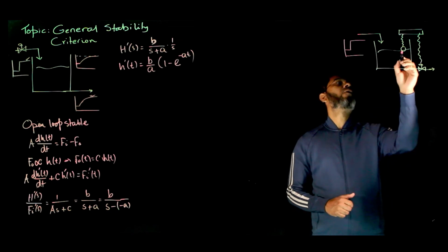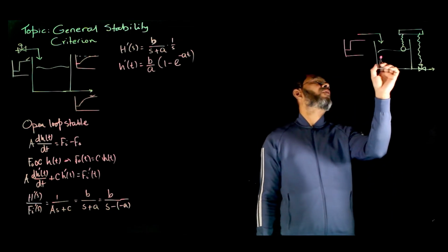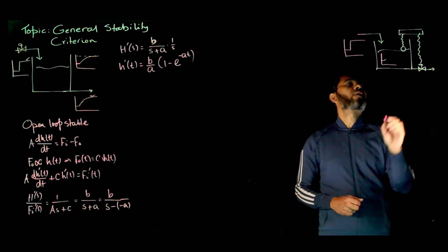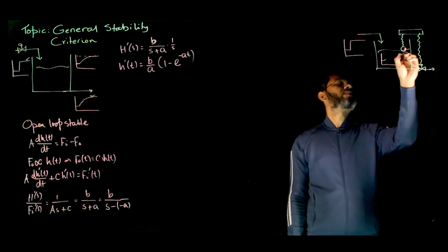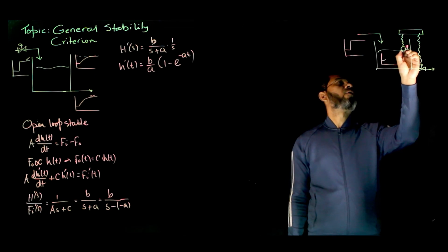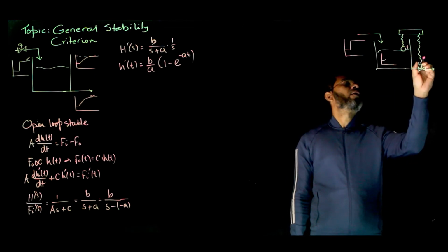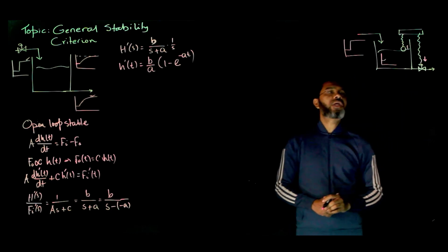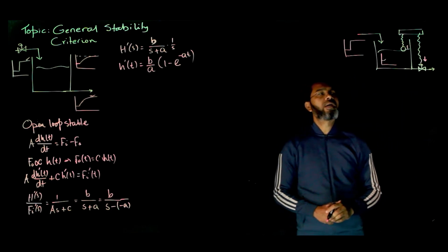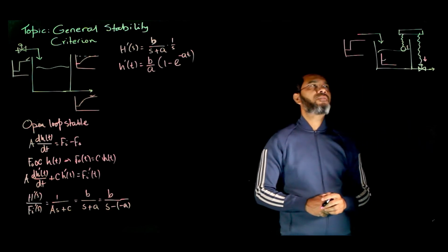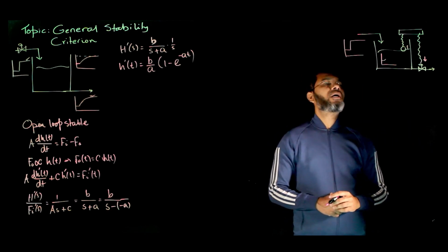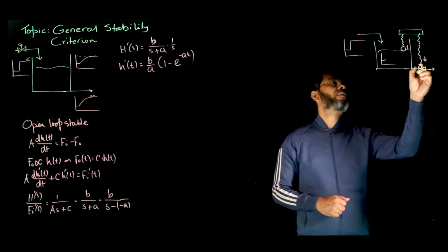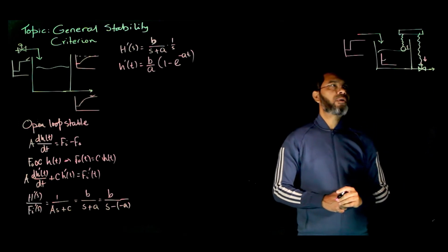We say that the level will go up. So for this case, the level will start going up. So when the level goes up, with this spring configuration, the float goes up, and that will cause this spring to go down and close the valve. Okay, that is just a simple physical configuration that's designed in a way that if the float goes up, then the valve goes down, meaning the valve closes.